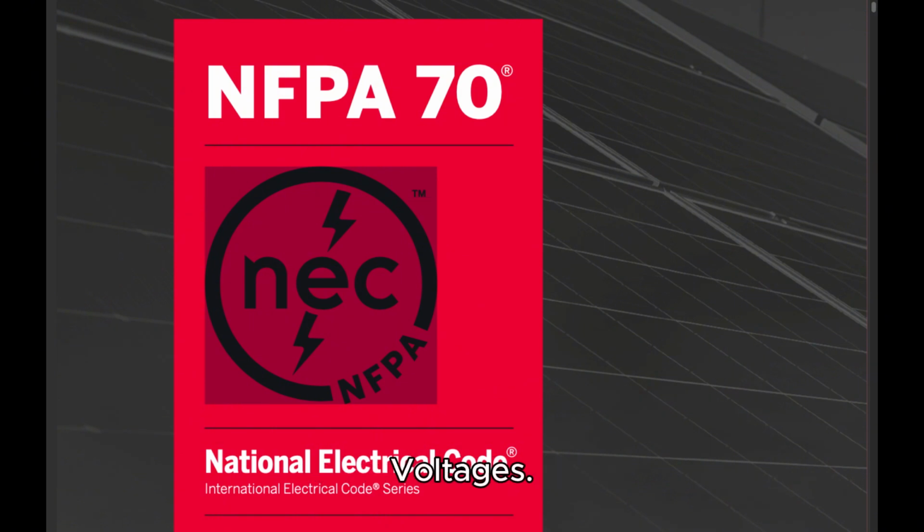110.4 Voltages. Throughout this Code, the voltage considered shall be that at which the circuit operates. The voltage rating of electrical equipment shall not be less than the nominal voltage of a circuit to which it is connected. 110.5 Conductors. Conductors normally used to carry current shall be of copper or aluminum, unless otherwise provided in this Code. Where the conductor material is not specified, the sizes given in this Code shall apply to copper conductors. Where other materials are used, the size shall be changed accordingly. Informational note: For copper-clad aluminum conductors, see